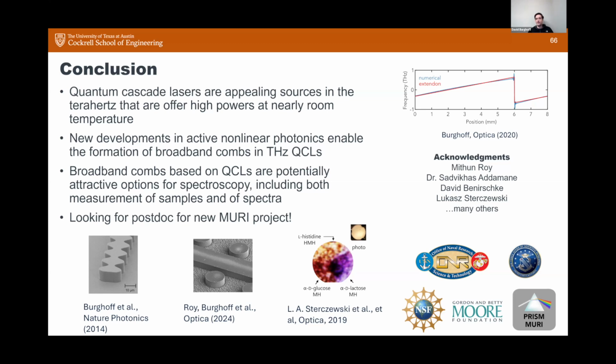I don't know if you necessarily want to do that because the repetition rate is already quite high for a lot of these systems, on the order of 10 gigahertz, let's say. So if you're talking about skipping every other line, every third line, every fourth line, you're looking at very high repetition rates. In that case, it's hard to do any applications with those states, right? You don't have that many lines available. Your lines are all spaced by a huge amount. If you wanted to cover that space in between, you'd have to tune everything around, which maybe you could do, or you have to have a very fast detector, with 20, 30 gigahertz of bandwidth, which is already a challenge.